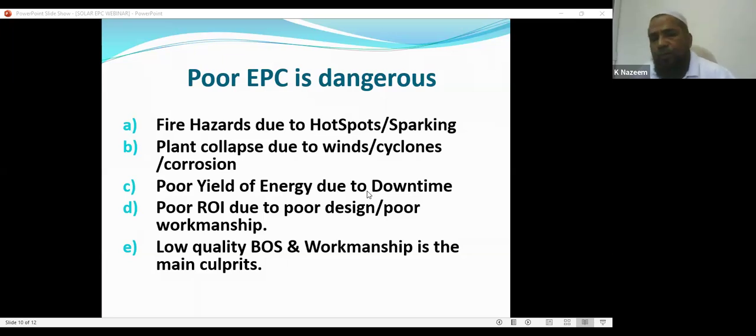Then he has called so many UPS vendors, traders. Everybody has failed. They are not able to identify the reason. So when Ramakrishna went there for analyzing the problem, he noted that the DC cable from the UPS to the batteries should be less than 2 meters. But in this case, it was more than 10 meters.